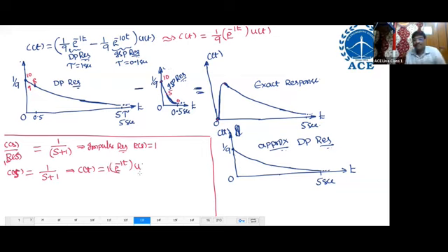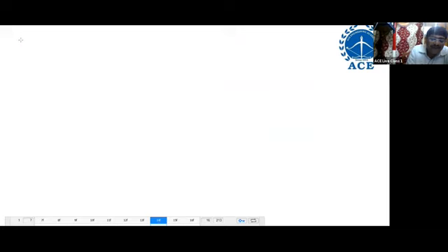What I told: when I consider the two poles, I got 1 by 9 e power minus 1t. When I neglect the insignificant pole, I find the response 1 e power minus 1t. Are both the same? No, it is different. That means this is wrong. It is not correct. So what is the equivalent first order system? The insignificant pole should not be neglected directly.